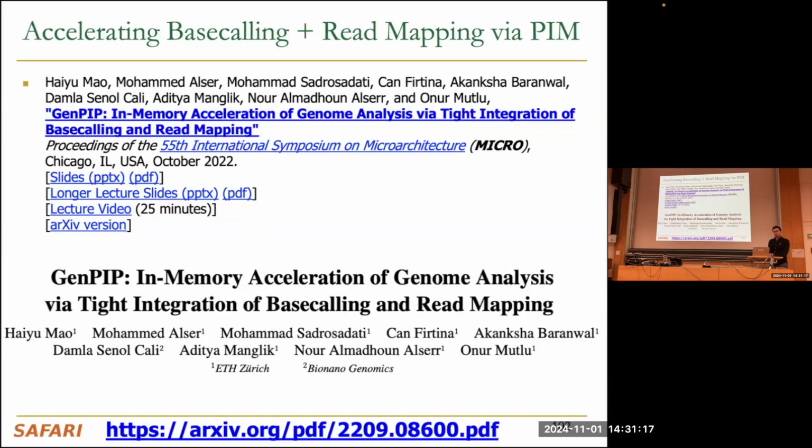Between the two accelerators. Yes, but this work still has data movement between these two accelerators. We are overlapping, exactly. And by being able to decide to reject early, you're also reducing the amount of cycles that would have been wasted otherwise. So that early rejection reduces it. It doesn't minimize it to zero, but it reduces towards that goal. And the decision on early rejection is taken during processing, after some set of chunks have been done. Exactly.